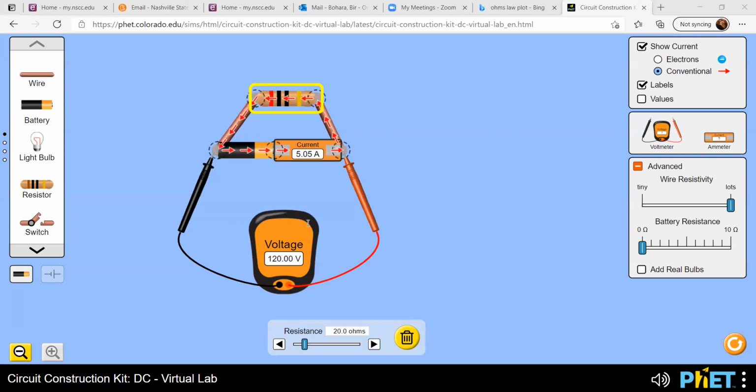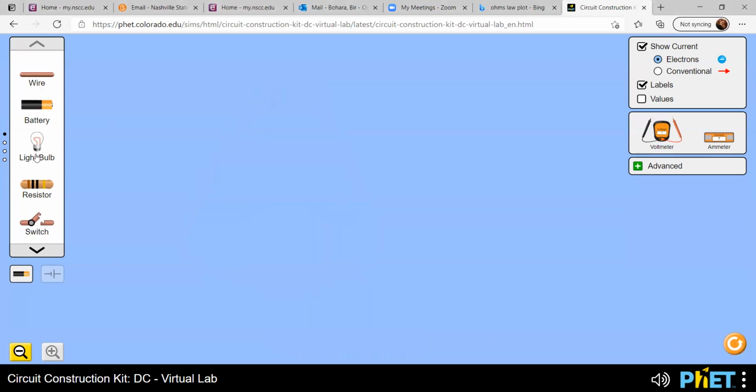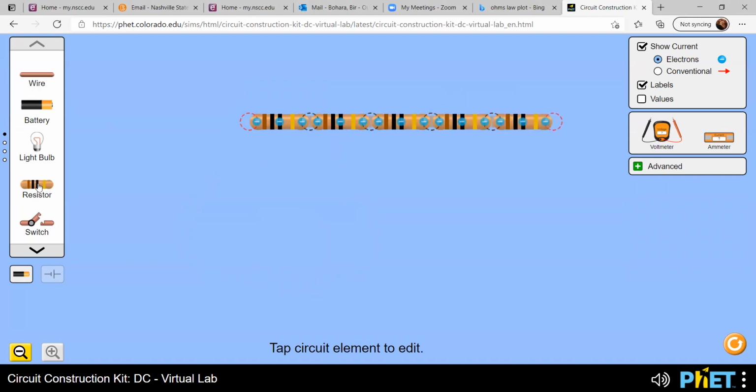Make sure voltmeter should always be connected across, right? Parallel. And ammeter should be connected in series in the circuit. This is the general norm, okay? So let me just get back everything. And first put these resistances in series. I need, according to manual, I need 8 resistances, 1, 2, 3, 4, 5, 6. 1, 2, 3, 4, 5, 6.